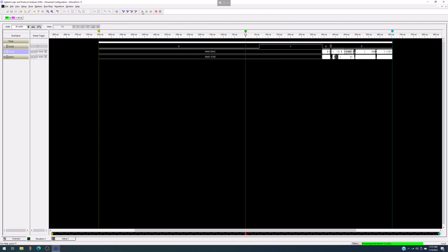But if I keep running this, now it's at E0018 and it read something. Now we're back at maybe 5AC, but the data didn't quite look right. So let me see if I can get back to another 5AC. And now we have a 1C50. So 1C50. So here's 1C63. So it's gone from 1C50 to 1C63 as I came around, and I'm just manually capturing here. So that just shows me it's incrementing what's in that RAM location at 5AC.